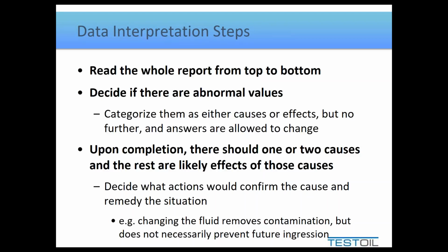So many times people see bad data on a report and they schedule an oil change, and while to be fair, it will correct the data, it didn't actually fix the problem. It's just putting fresh oil in. So we need to say, what is the true cause and what would prevent it from recurring? We still might change the oil, but we need to take some extra action here.